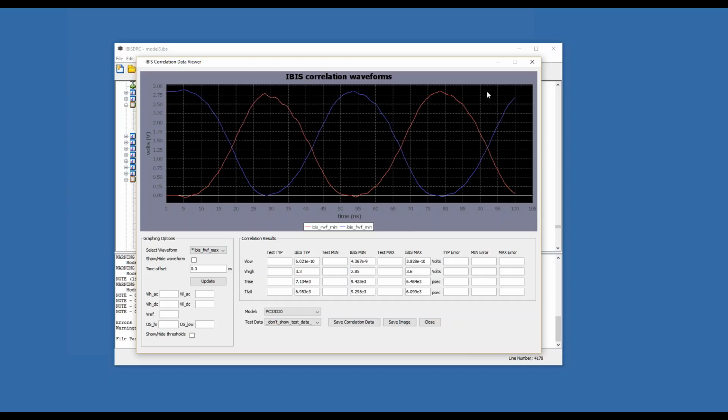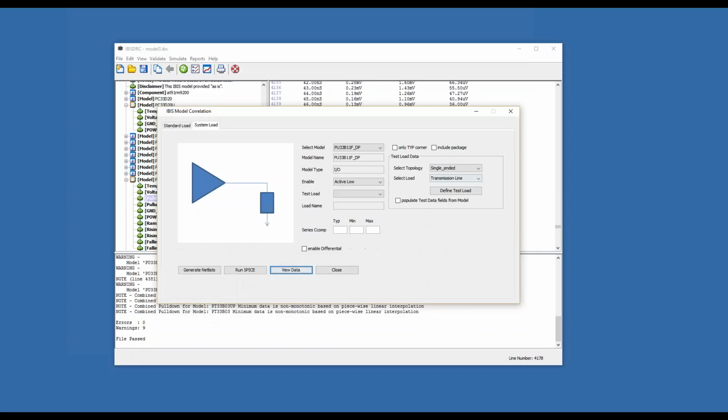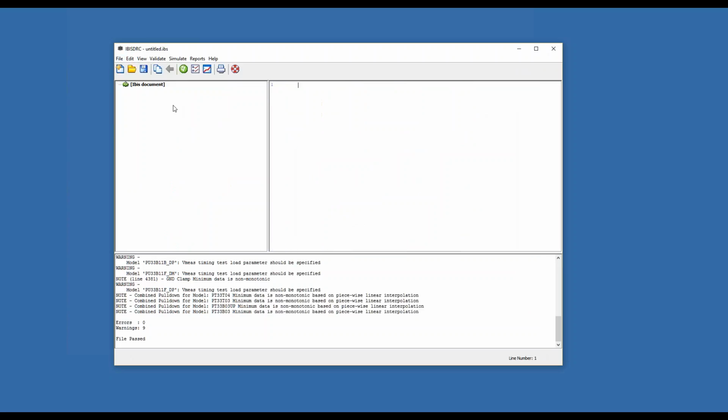So this is sort of an advanced thing, where even though you're working with IBIS models, you can start to do some design simulation, some design analysis. You can start to figure out, what can your driver drive in terms of a system load? Would you need termination? And you can quickly do this type of stuff in your tools, even before you start to do your full level simulation. And so that's just sort of ways that you use your IBIS models to go beyond it. Okay, so that was that one, and I got one more left.